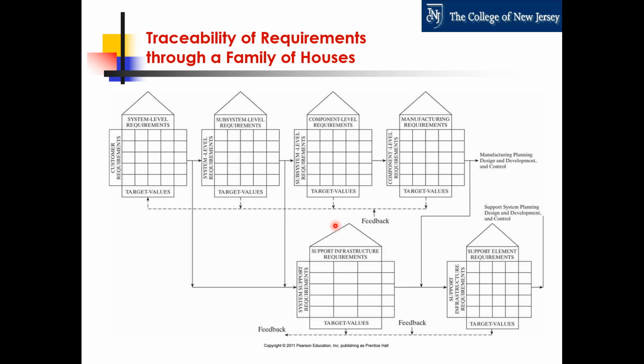And if that's what happened, then you need to do a house of quality for that subsystem. Do a need analysis, do a house of quality, and what emerges from that is a family of houses of quality with built-in traceability of requirements. Okay? So, just to highlight the fact that we have to do this also at the subsystem level as the hierarchy emerges.